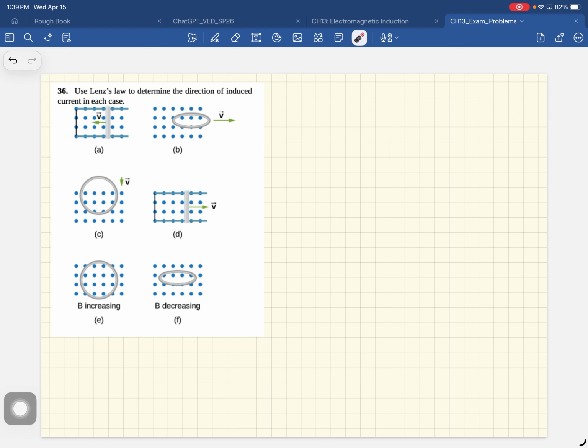If the strength of the field is that, what is the average induced EMF in the coil? The EMF induced in the coil is delta phi over delta T. We'll just calculate the magnitude, so NBA over delta T. The final flux was 0, so final minus initial, and then you take the absolute value.